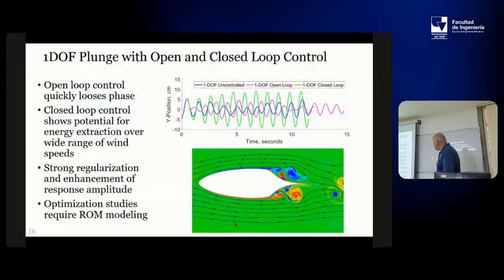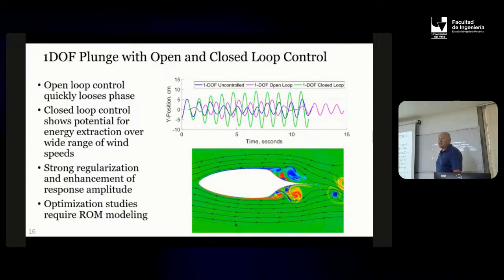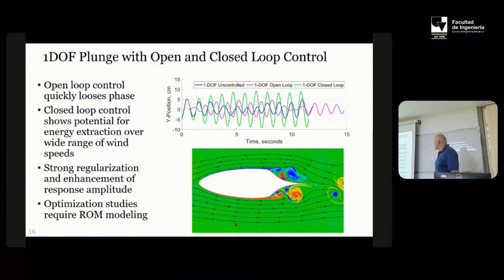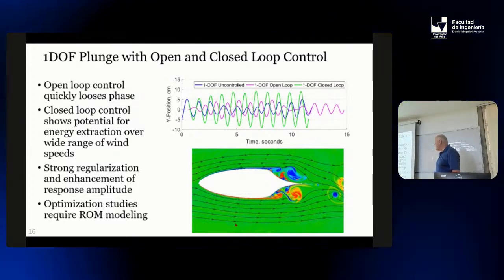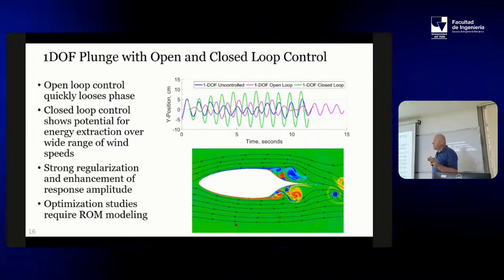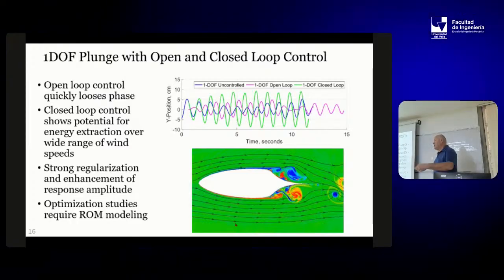Yeah, because in the end it was the development of the reduced order model, because all this high fidelity stuff is very expensive. You can run a case for maybe days or weeks, depending. But the reduced order model usually develops some kind of analysis, which is basically more sophisticated, like panel methods. And with this, you can actually get much faster, very fast. So you can do design optimization.